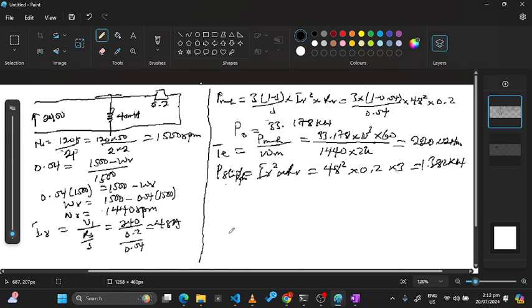But the torque is constant, so we are still maintaining a torque of 220. So we know that Te is equal to what? 3 V1 squared, the pole pair times, we take this R out because it will cancel the square down there, then we have omega slip, all divided by omega E squared, then RR.